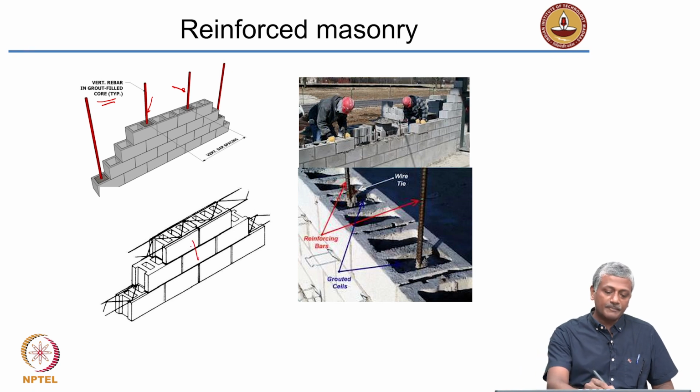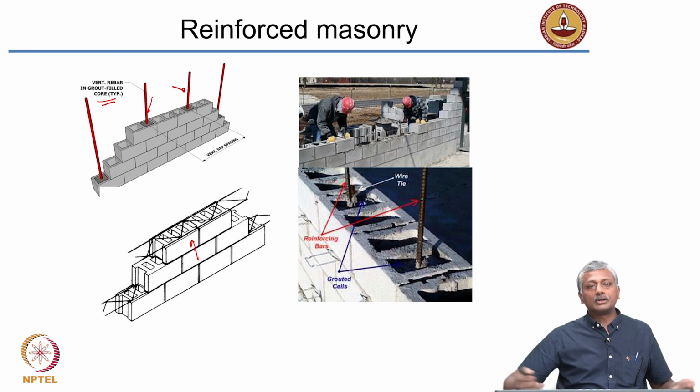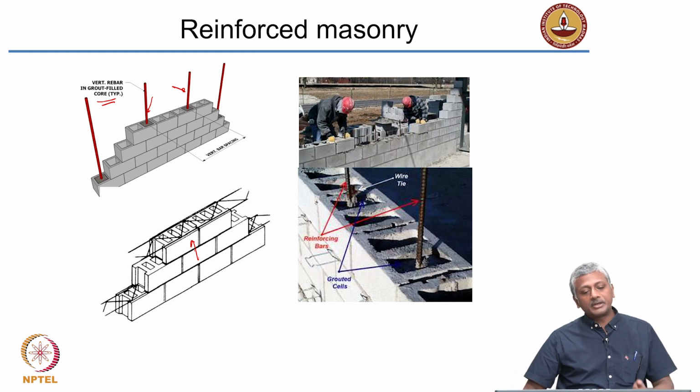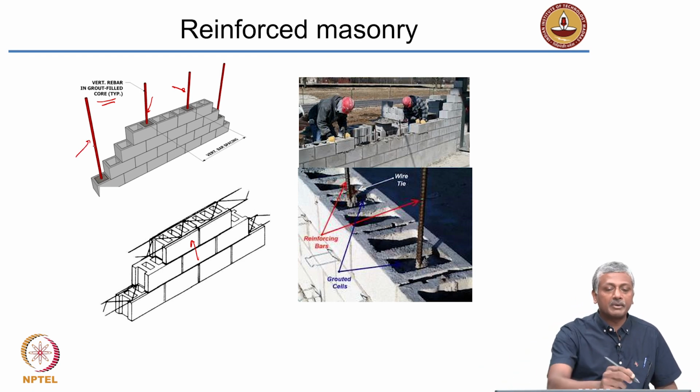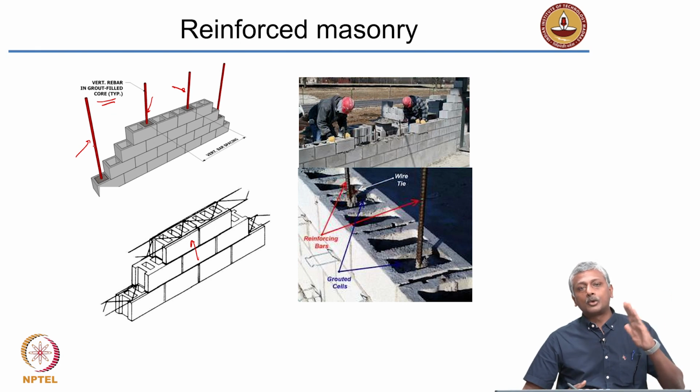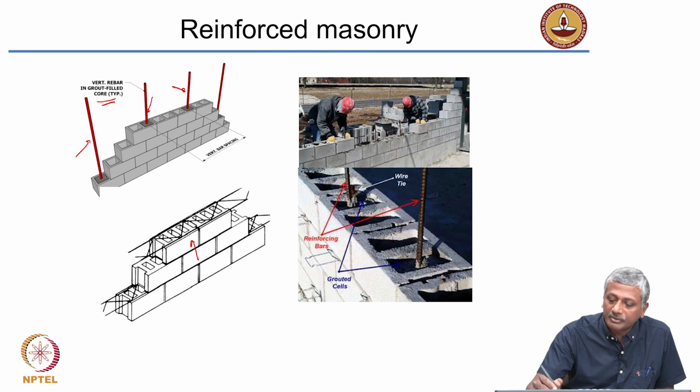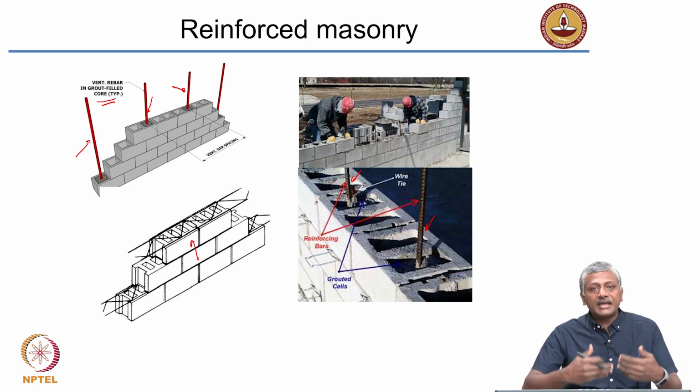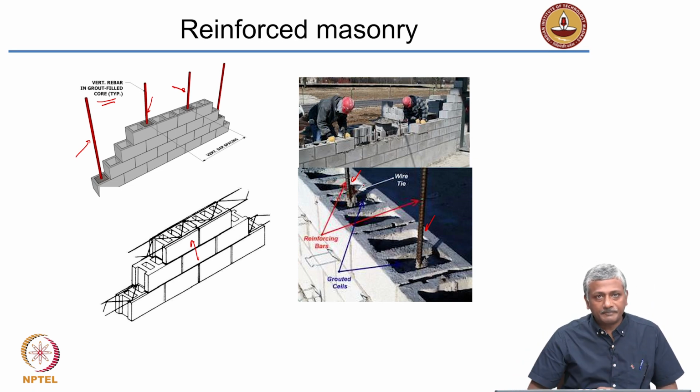Again, you see here, reinforced concrete block masonry can also get horizontal steel to reinforce it, but mostly we are talking about these vertical steel members that impart the lateral load resistance for the wall. Just to give you an example of real construction, you see these blocks where the steel has been inserted not in every cavity, but in every third cavity.